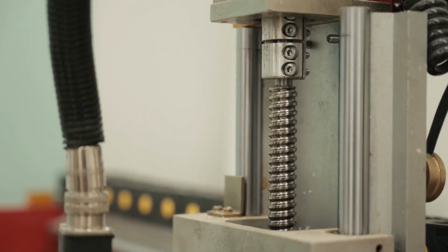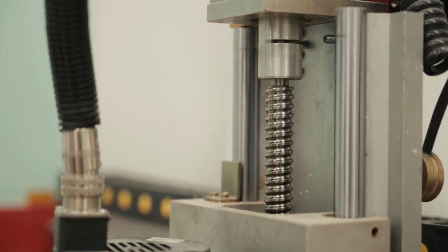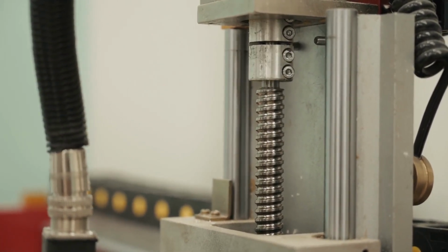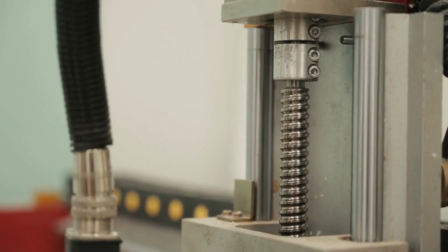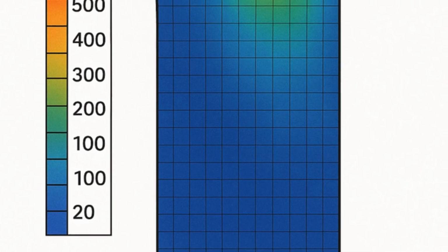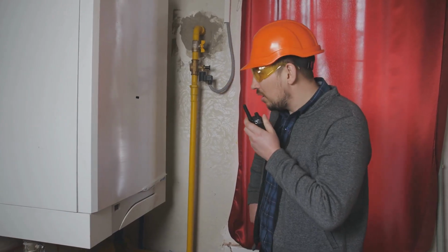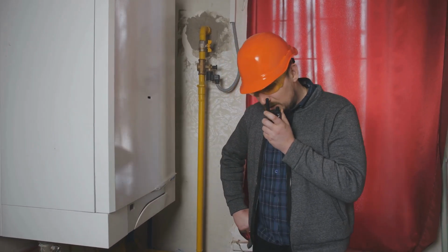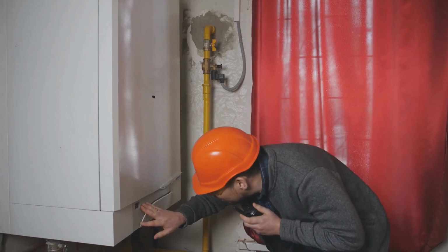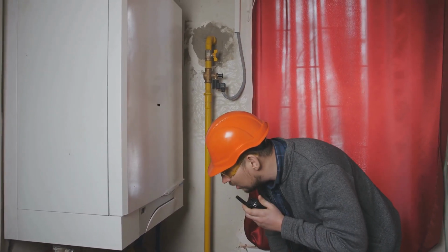The SN approach is often suitable for components like rotating shafts or springs that experience many cycles under relatively low, primarily elastic stresses. Its limitations appear when local stresses exceed the material's yield strength, leading to plasticity. For pressure vessels, the regions around nozzles or openings can experience high local strains during pressure cycles. Here, the epsilon n method is far superior.